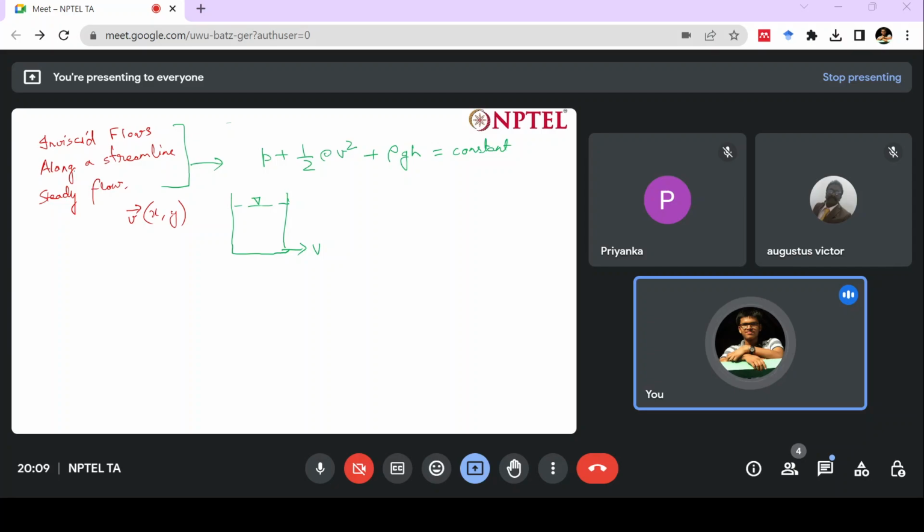So in this case, you may ask how we define the streamline. We can simply assume that this velocity is uniform in the orifice. This is completely an inviscid flow. The viscous effects are not important. Since this is a free surface and fluid particles are moving out, there must be some point on this free surface which connects to a point in the outlet using a streamline. So we can simply use our Bernoulli's theorem to find out this velocity.